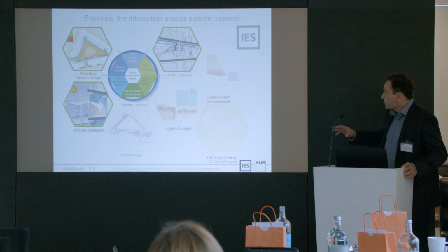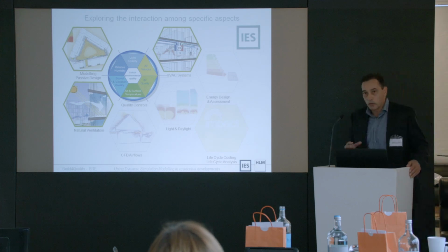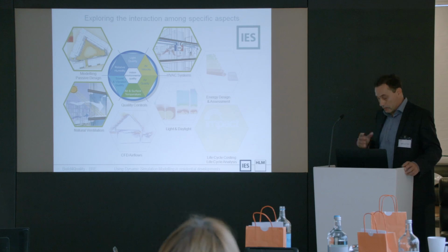These are the natural ventilation connected to the mechanical ventilation, and some winter gardens, which are extensively provided in the development. Natural ventilation will be used whenever the outdoor temperature is suitable for that. That means whenever it is higher than, say, 16 degrees, more or less. Otherwise, the mechanical ventilation will kick in.